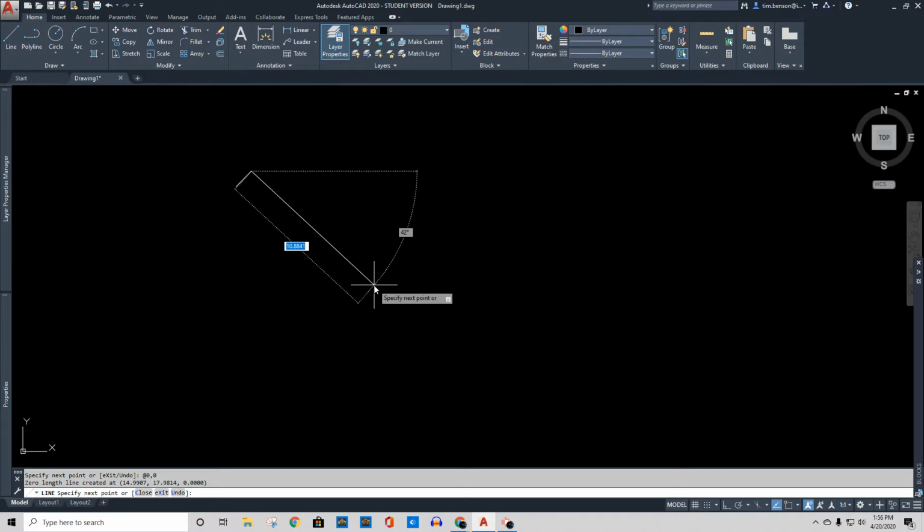Now, as I'm working here, I can also tell it to go, say, 2 inches, tab, and I want to give it a bearing. So I'm going to give it a bearing of, say, 175 degrees. That's not quite pointing to my left. Now, straight right is 0 degrees and it counts around counterclockwise, follows your thumb around. So when I do that, it's going to make a diagonal line that goes up and over a little bit.